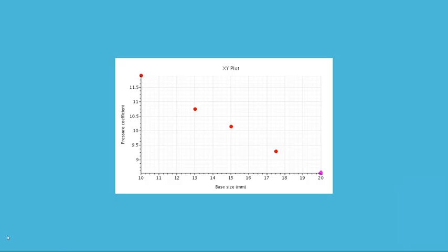In this example, we will perform a mesh refinement study where the same case is run successively with a mesh size of 20 mm, 17.5 mm, 13 mm, and 10 mm. As the mesh is refined, the solution and the pressure coefficient of the case become more and more accurate, but only change a little between designs. It can thus be more efficient to initialize a simulation using a finer mesh with the results from a coarser mesh. This would also be beneficial for other parameters, for instance inlet velocity.